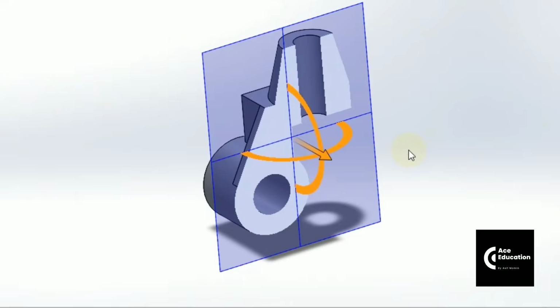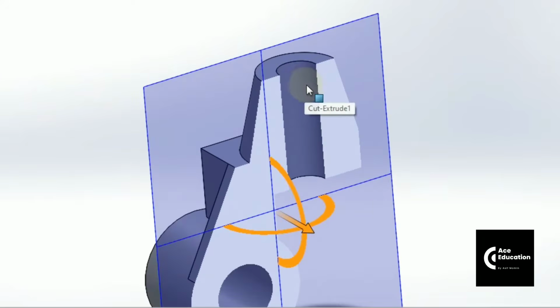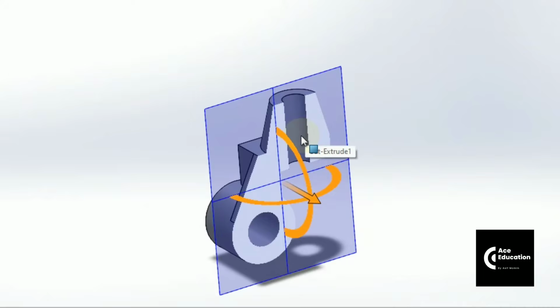Hatch lines are supposed to be shown at an angle of 45 degrees and should be equispaced. You can see the white portion is the surface where it is being cut, but you can observe that inside this hole, this part is not a white part, this surface is not being cut, so it is not shown in white itself. So we are going to leave this surface as it is, and wherever the surface got cut, we'll show that surface by hatching lines, except this rib, because the rib is an extra plate that is added for strength purposes.